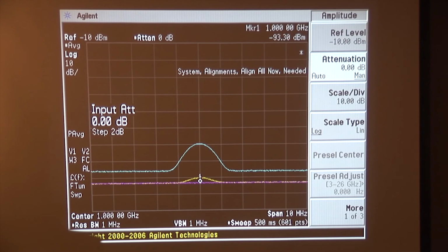See, at that point, my gain isn't really quite as high as I want it to be. So I'm going to take out a 3 dB pad. So now I've got 20 dB. The reason I'm off a little is I was just adding the decibels. So technically I need to use the anti-logs to do it right, but I was just doing it in my head. So that's all right. It just takes you a second with a couple of attenuators to get this thing adjusted properly.